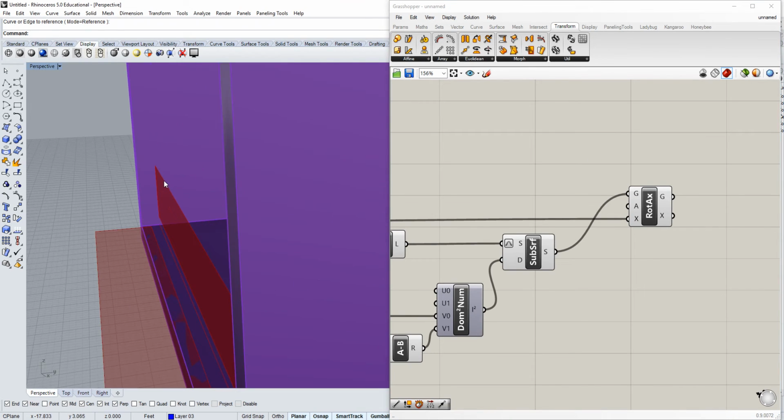Now, I'm not going to want it to tilt very far. I only want it to tilt just barely outside of its original position, but not quite as far as the front face of the building. So it might be 2-3 degrees. So I'll just make a slider from 0. I'll start at 2.55 to a value of 5 degrees maximum, probably.